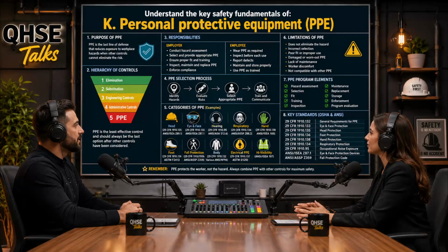And the 6th hazard. Oxygen deficiency. Oh, that's a critical trap. An air purifying respirator cannot create oxygen, can it? No, it cannot. If you enter a confined space where a displacing gas has dropped the ambient oxygen level below 19.5%, a filter mask will do absolutely nothing to save you. You will asphyxiate. You must use an atmosphere supplying system in that case.